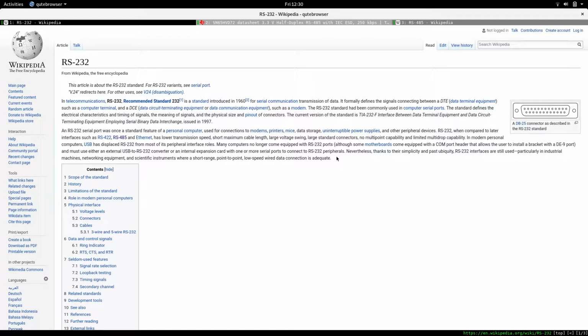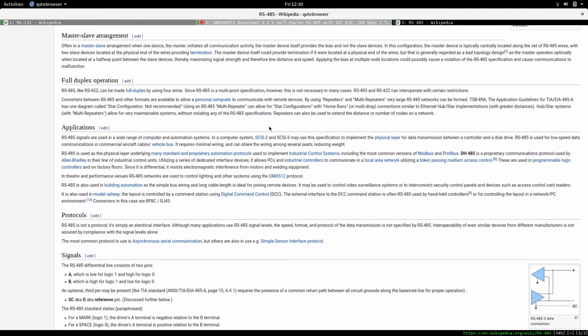It's also, because of its voltage arrangement, susceptible to electronic noise on the line. So if we were looking at the signal line and I turned off a kettle or some electronic device, then there might be a voltage spike, and that would cause a spike on that serial line, and that would be interpreted as a start bit, and the device would read that as a start bit, and assume that that was a transmission of a data byte, which was 00.